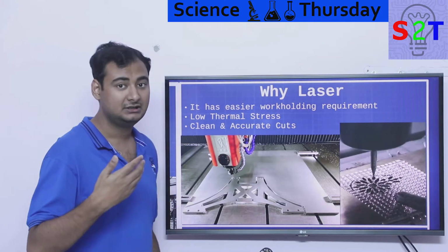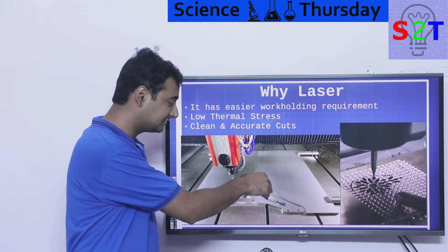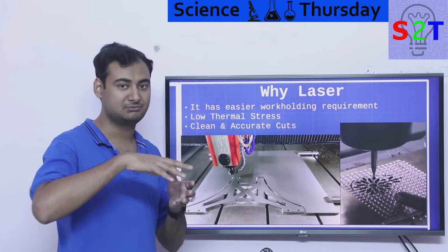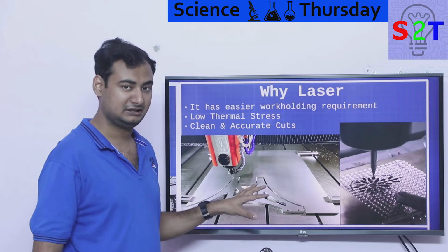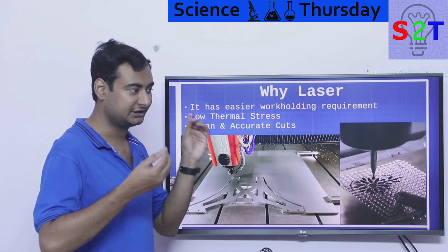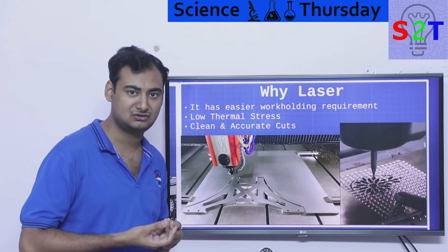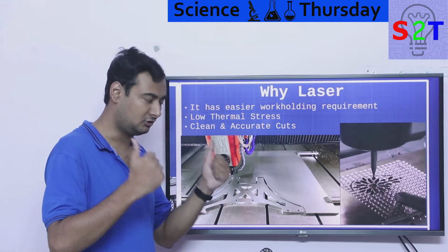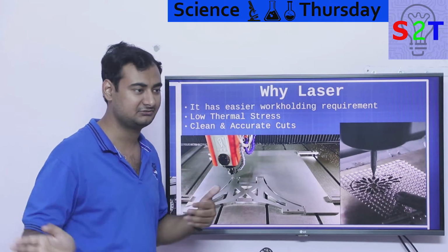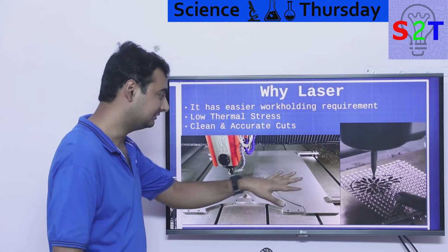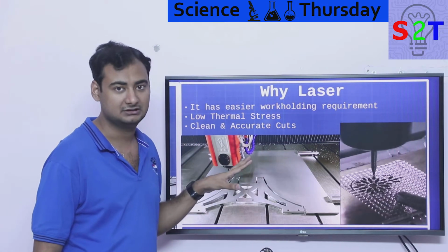And sometimes if you are doing fancy cutting, you also have to leave what we call tabs. These make sure that your object does not move around. So you may say, okay, 500 watts of spindle power is not enough, let's put in a 2 kilowatt spindle. Awesome. Will it do the job? Awesome. It's just that the moment it starts to go through the material, it will remove the material itself, so you have to clamp it down. That's a very difficult thing.